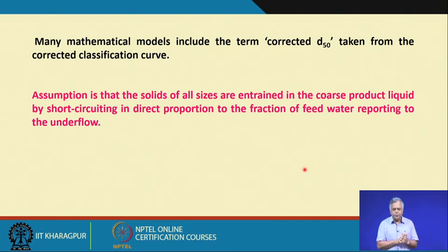What is that assumption? The assumption is that solids of all sizes are entrained in the coarse product liquid. Whatever water is reporting through the underflow, particles of all sizes are entrained into it in a certain amount.